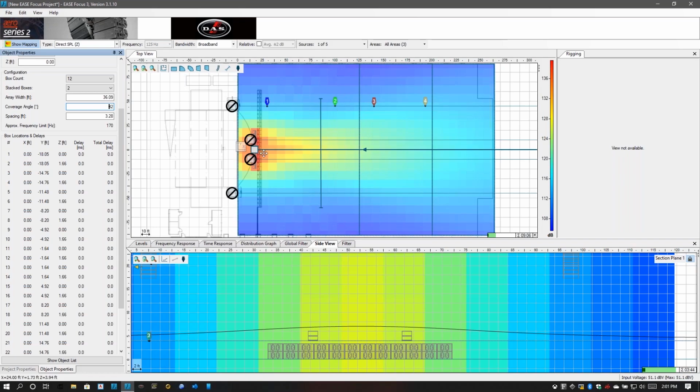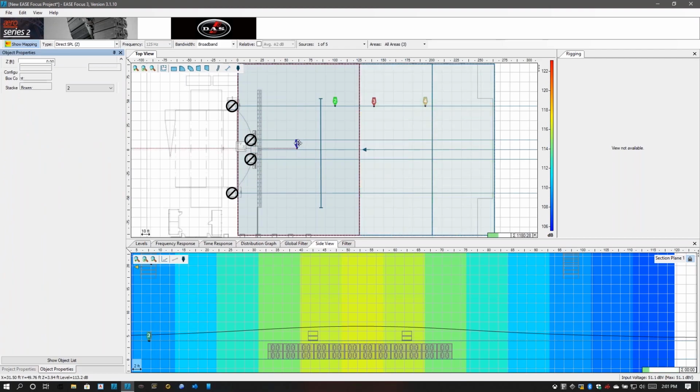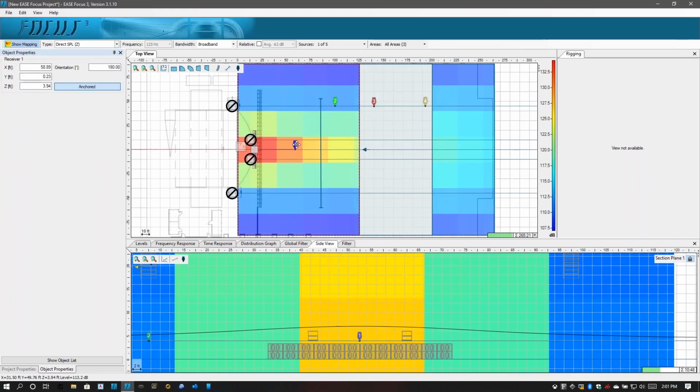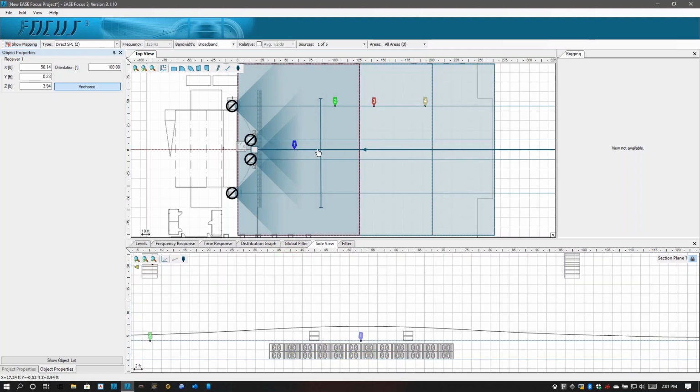So we are now going to grab these microphones and see how it all changes in our frequency response. I'm going to set one dead center on axis to the subs, and make sure I know what distance I have placed it at. It looks like 41 feet or so.